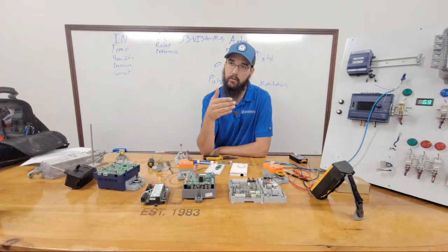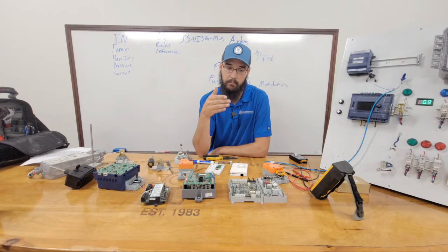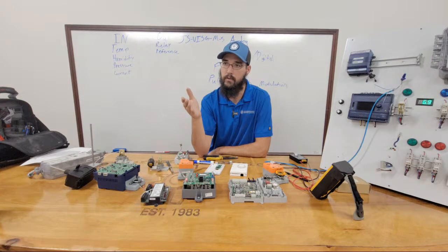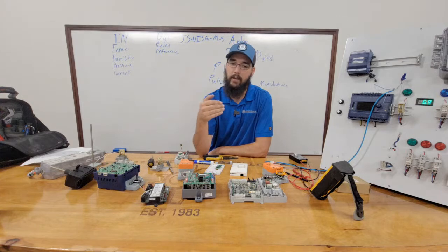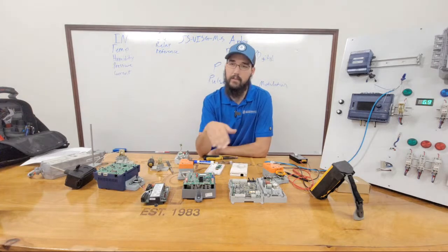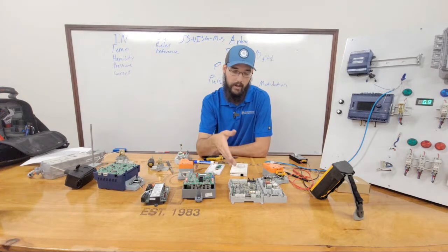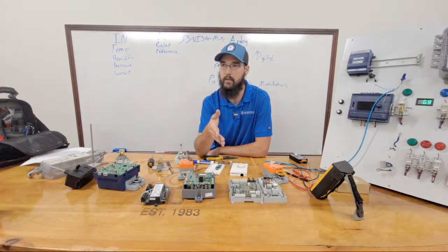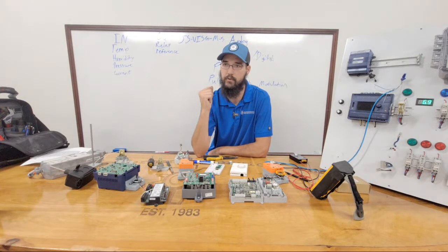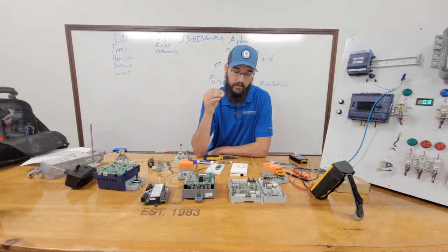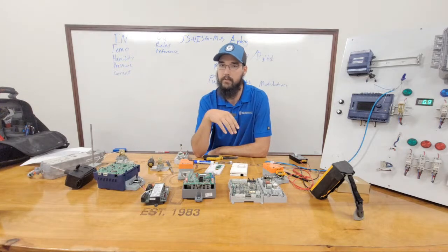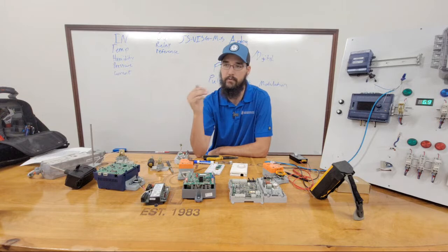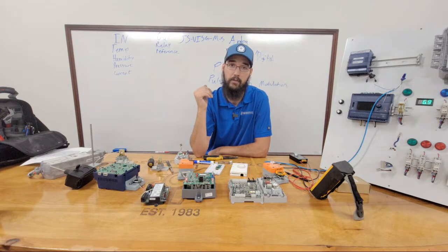So at that point, the building's control people, or yourself if that is you, can hook up and just reassign the output. So say you have 5 outputs or analog outputs on that controller, and output 3 is the one malfunctioning, but output 5 is open and available and not being used.